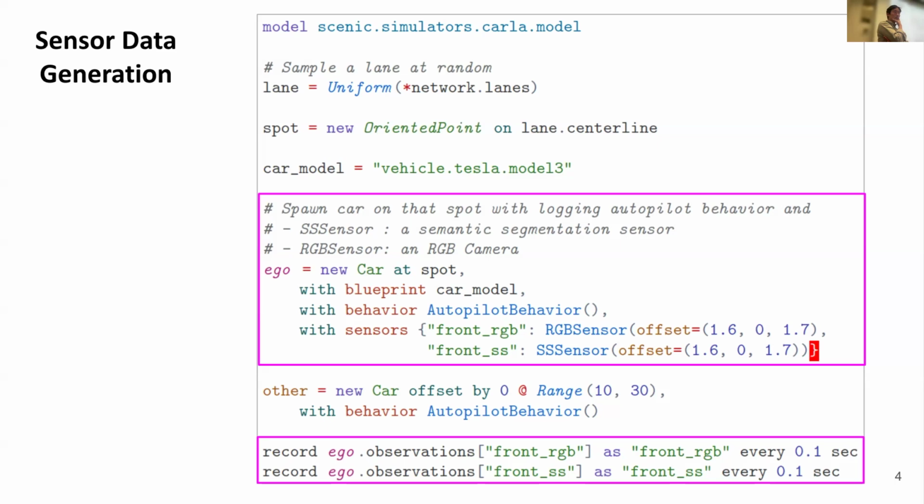Yeah, I mean, real sensors have noise, they have inertial delays and things like that. So, first of all, the simulator has to be able to capture that, and then we have to expose it within Scenic. And secondly, I think you need to know about these differences in sampling rates. Maybe even post-processing, we can deal with it if we just check out the simulation. I'm not sure. As Daniel was saying, in the worst case, you set the Scenic time step to be something very fine-grained, and you capture everything and then you post-process. Yes.